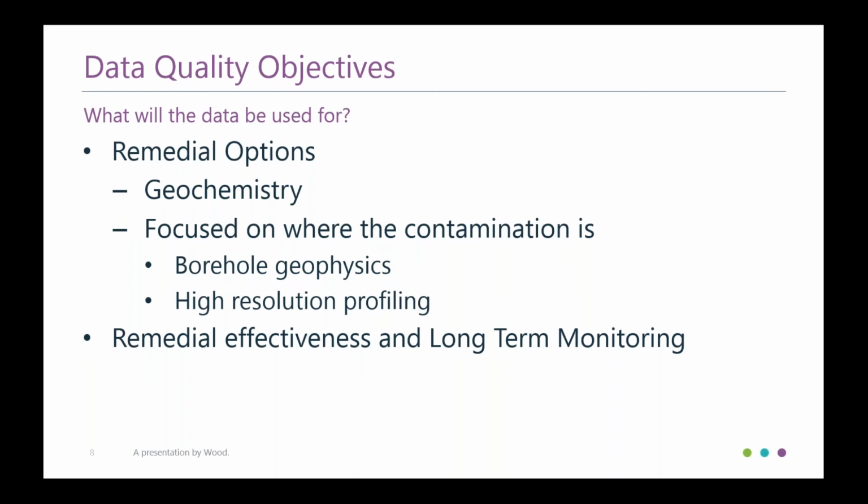And then the last one I had was remedial effectiveness and long-term monitoring. After you're done with your remediation, how are you going to evaluate whether it's being effective? Trends, are you expecting trends to go down? So you need to make sure, again, these wells are located in a position that can give you this information. Again, you may or may not be able to use wells you've already installed during the investigation. Again, it may mean going back out and putting in more wells to figure that out.